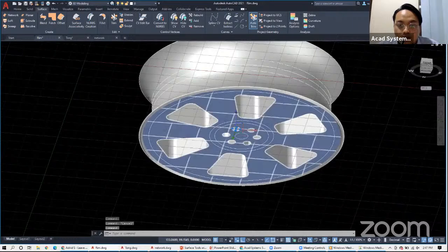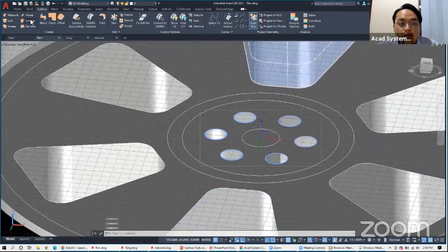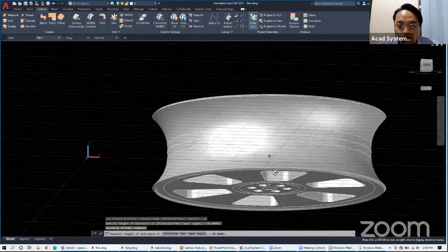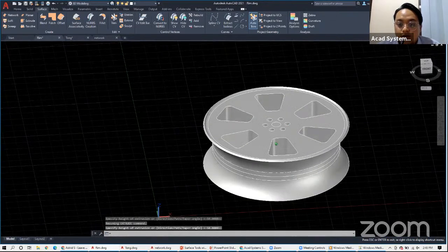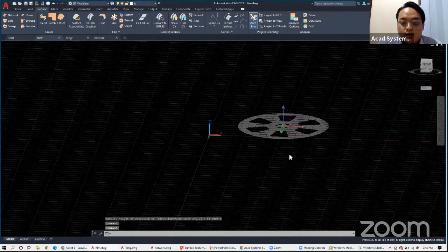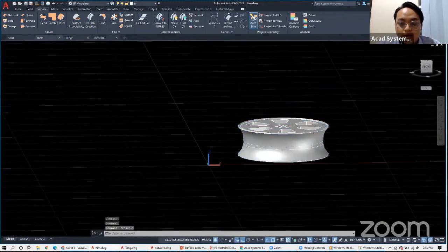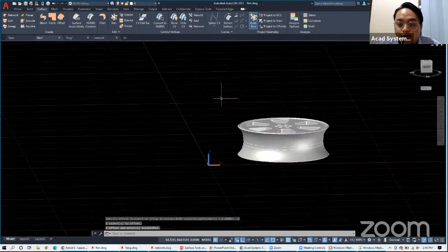So just click on this. Okay. Then just extrude. Do the same. Okay. Just select here. Okay. Right now, I'm going to thicken this a little bit. I'm going to use offset. Okay. Let's say here offset. Okay. Changing the direction here for 0.5.